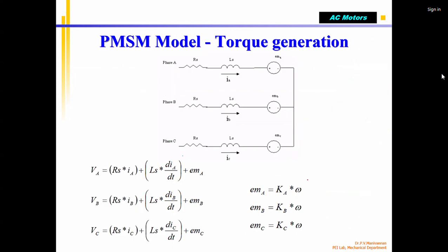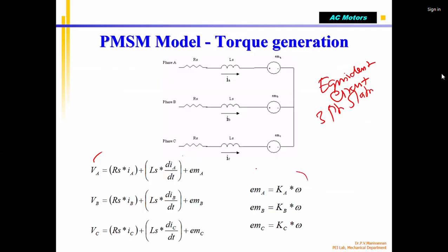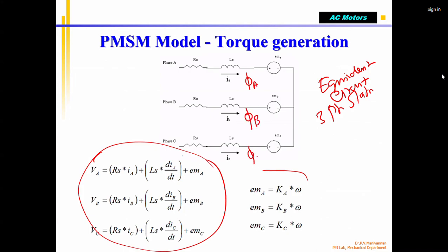Okay. So now that you know this equation, please note down this equivalent circuit called equivalent circuit of stator. Equivalent circuit of stator. Stator winding, three-phase stator winding. Okay. So this is voltage, these equations are expected in the exam. Okay. So now, because you supplied this, the rotating magnetic field is created because of the three-phase voltage applied, current is flowing. It generates phi A, phi B, and phi C. And this being three phase, it is going to the phi R.